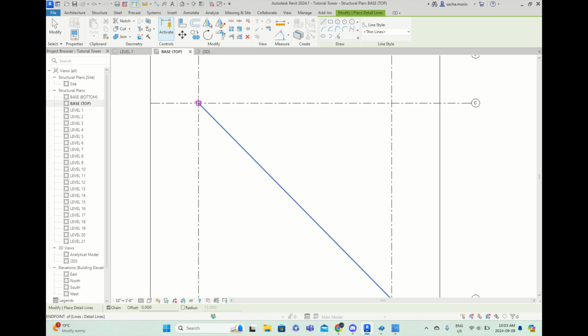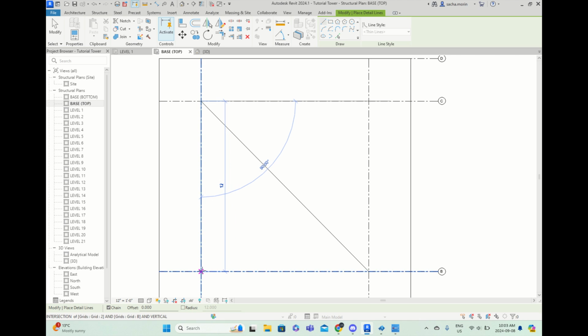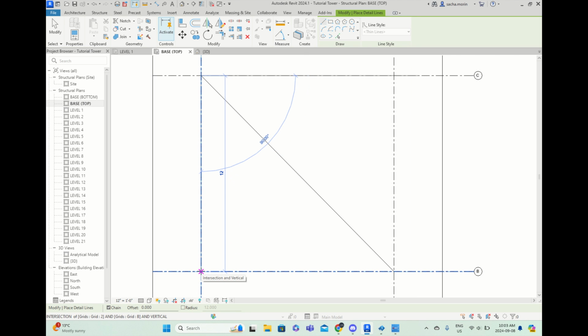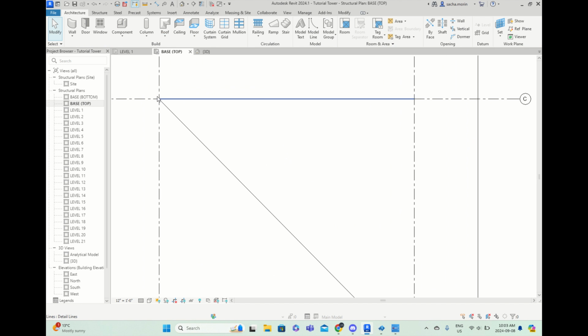Let's assume that the base of our column, or our allowable floor plan that we can build in, is 12 inches, as you can see on the top there, by 12 inches, as you can see kind of in the middle of the screen, a little bit on the left. So if I make a design line going kind of on that perimeter, I can use the offset tool to offset myself a length of a beam and then a length of half of a column so that I can be at that center point.